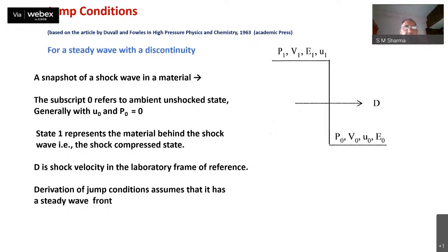The wavefront is either a discontinuity or a steady wave with a finite thickness. We discussed last time that thickness is basically decided by the competition between the non-linearities of the material and diffusive interactions such as heat flow or defect generation and so on.